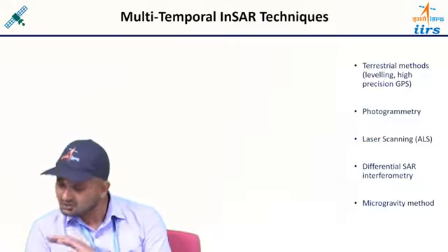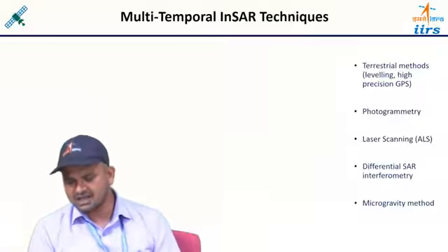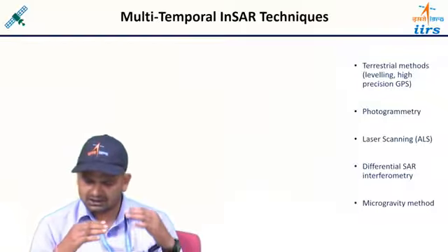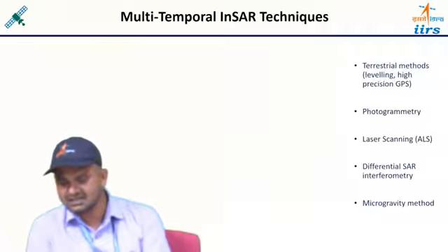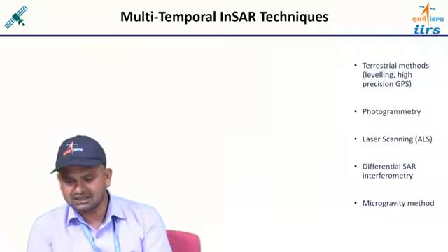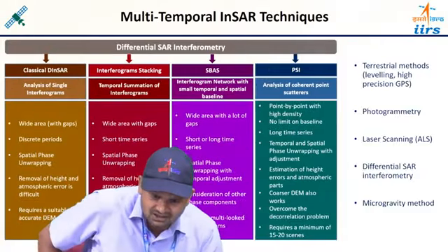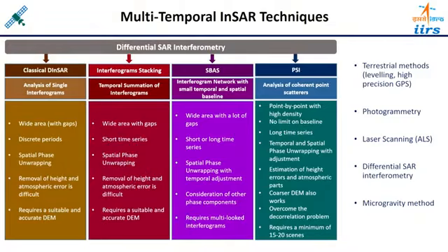So accuracy-wise we are not losing anything. Additionally, we are having continuous data and a more frequent data set, so that the deformation can be monitored regularly. So many advantages of InSAR over the other existing techniques are there. So here you can see these are the differential SAR techniques. One is the classical InSAR technique, the second one is interferogram stacking, the third one is small baseline subset analysis, and the fourth one is PSI, persistent scatterer interferometry.